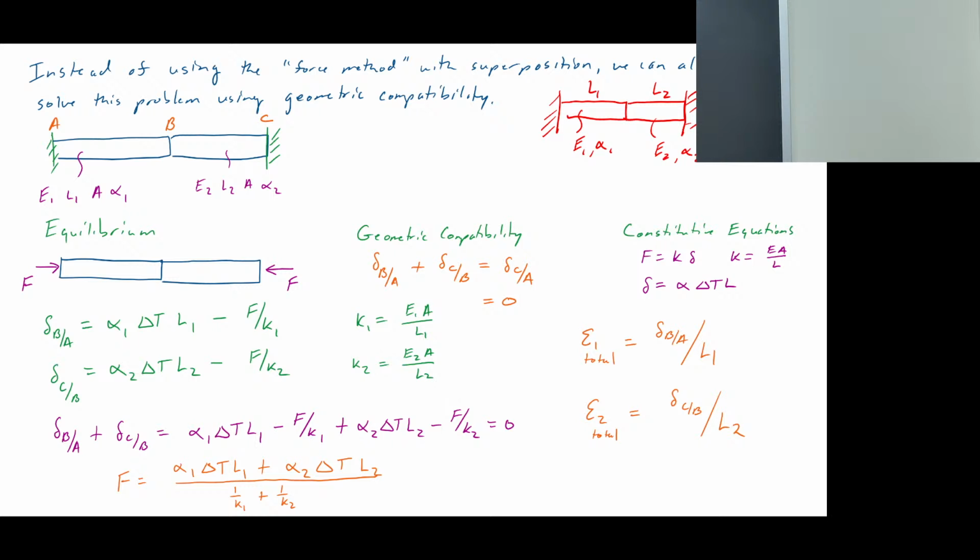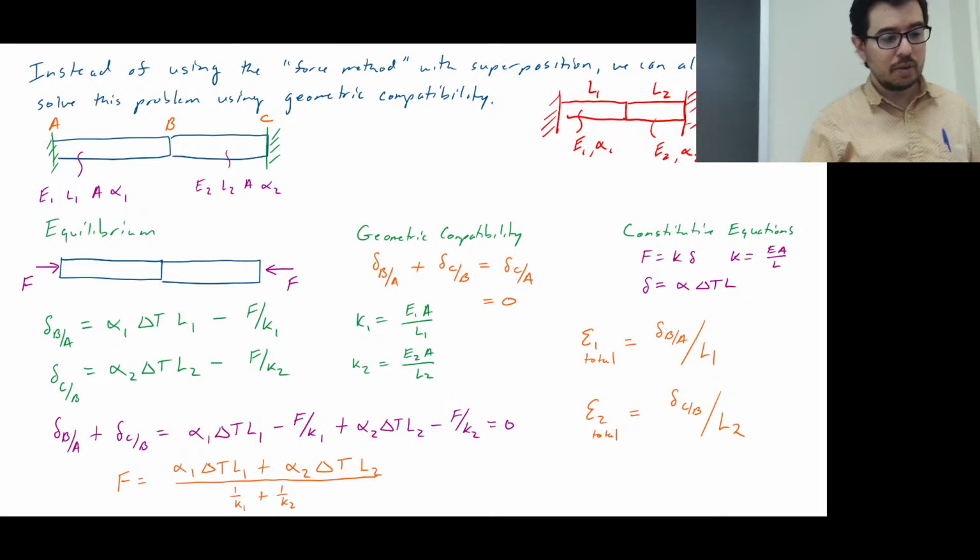You saw there was a negative one due to the force, and a positive one due to the alpha delta T. Well, this is going to likely have a positive strain, and this one on the right will likely have a negative strain, because it's pushing it to the right. So there are these interesting balances that we can think about here.